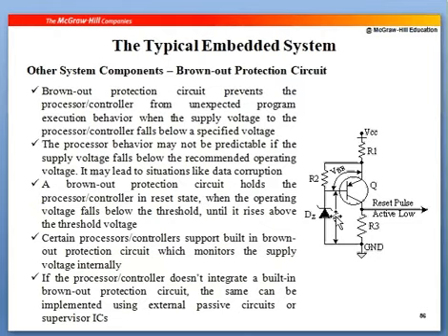When this transistor is turned off, you get an active low signal, and it is connected to the reset pin which receives an active low signal. When it gets an active low signal, the controller will reset or reboot the system. So just remember, the condition you require is VZ, the voltage across the Zener diode.